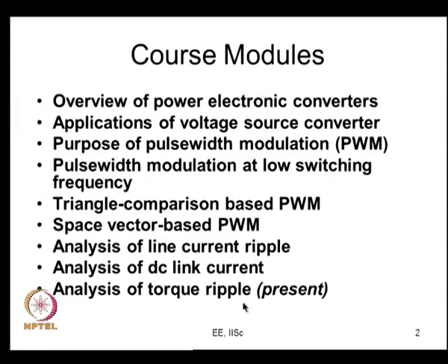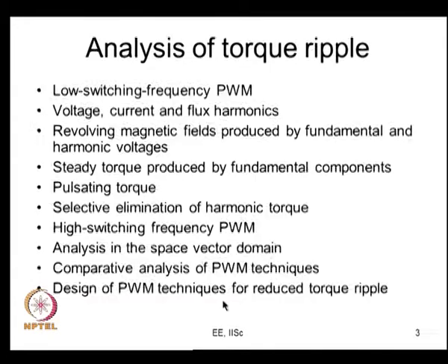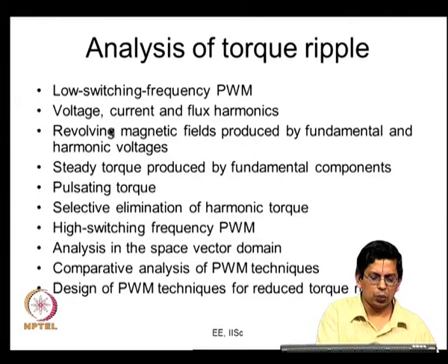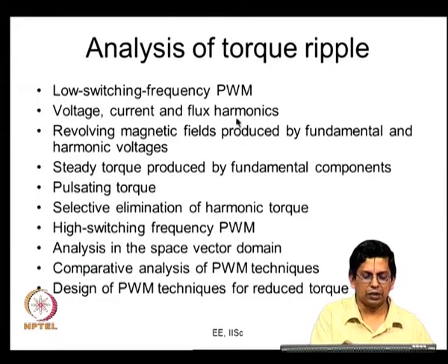So, for now we are going to look at low switching frequency PWM and analyze the pulsating torque. We might have a quick review on that if necessary, and then we will look at the voltage, current and flux harmonics when you are feeding an inverter not just the sinusoidal voltage, but also the harmonic voltages.